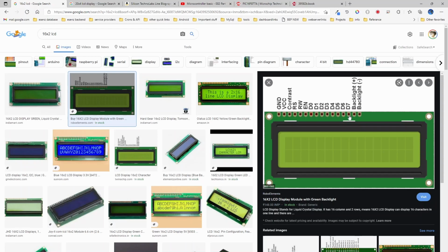So this is a parallel display, you have to send the display data in parallel, like 8 bits. Or there is another mode called the 4-bit mode, which means you will only use D4 to D7. So instead of sending 8-bit data at once, you have to split that into the upper nibble and lower nibble, the top 4 bits and bottom 4 bits, and send it on D4 to D7. So the driver which I have is for 4-bit mode.